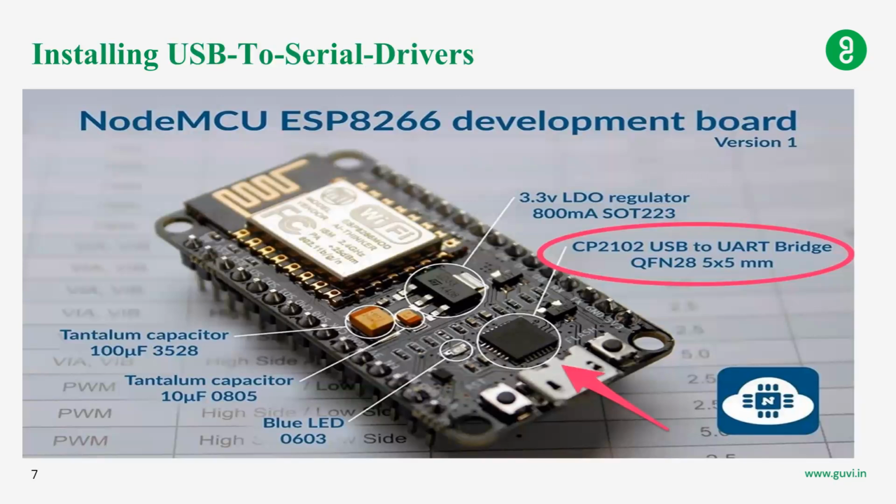Installing USB to serial drivers. Installing the USB to serial driver for NodeMCU ESP8266 is a crucial step when you want to program or communicate with your NodeMCU board via USB. Plug in your NodeMCU. Here is an example of the NodeMCU ESP8266 serial development board.